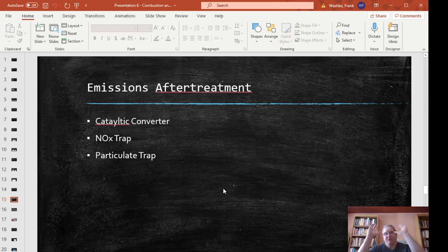And if you can see it in the air, you see smoke coming out of the tailpipe. Which one is that? It's not NOx, and it's not carbon monoxide. It is unburned hydrocarbons. So that was like, what do we do about the smog problem? What do we do about the HC problem and the CO problem? Well, you implement a catalytic converter. That was the 1970s.